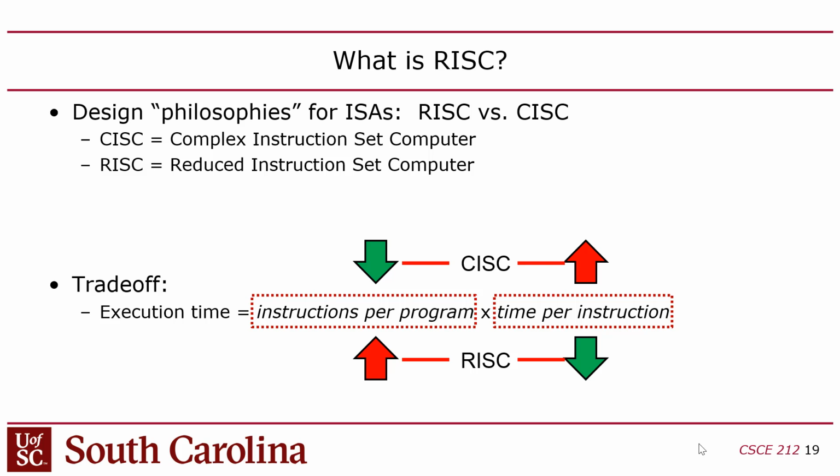But the idea is that if you make the instructions simple, you can make them fast. So you can chew through them really fast. And since memory is cheap, we don't have to worry about memory. On the other hand, a CISC instruction set architecture allows you to do a lot of work per instruction. The instructions are more abstract in the sense that they perform more workload. You'd have fewer instructions to make a program, but then you end up with specialized hardware that you don't use very much, right?